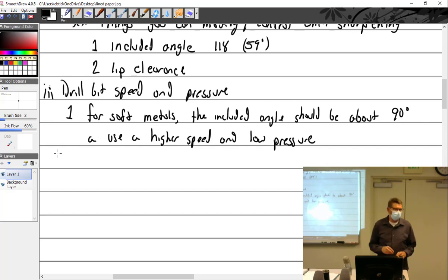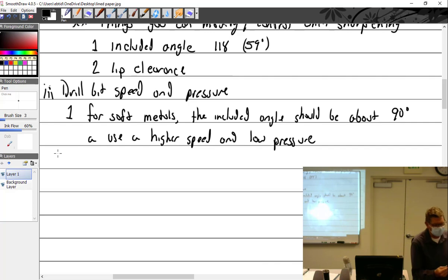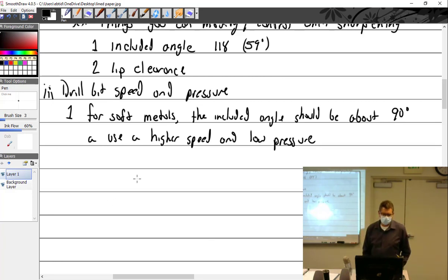And now it comes down to, do I want to turn the drill bit slow or fast? You're going to want to go fast, obviously. Harry's kind enough to bring in a plexiglass drill bit. It has what's called a zero rake angle, and there's no cutting lip on it. It's just a flat piece that scrapes its way through, so it has to be turned pretty fast. I want to get through it fast, before the windshield cracks. So softer metals, higher speed and low pressure.